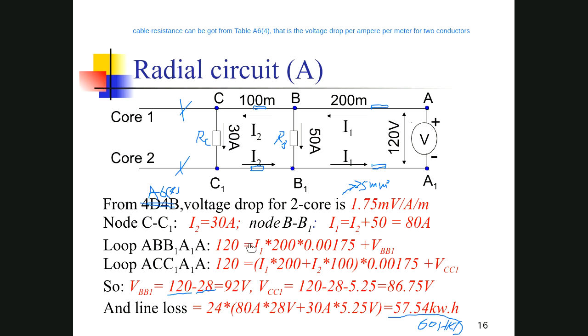So we usually have very long distribution conductors inside the buildings. For example, for a 100-meter high building, if we have the transformer room on the ground floor, we should use big cables to distribute electricity from the ground to the top of the building, so that the voltage drop on the distribution cables is small.